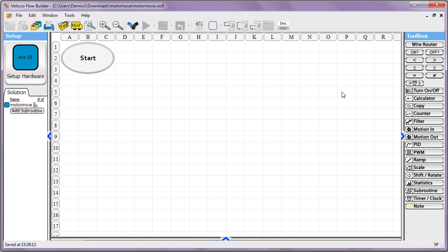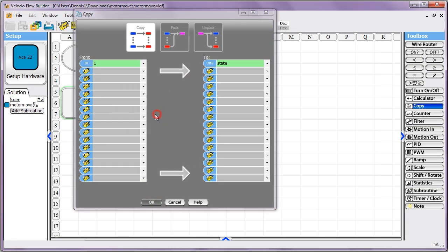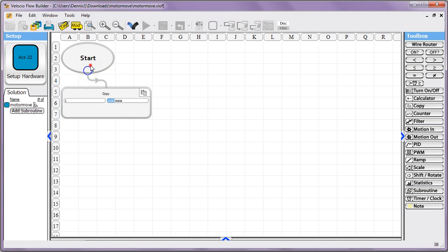And I'm going to set this up like a state machine. You can see in our other tutorials, if you go into the software tab under tutorials, some other examples where we describe state machines, but I'm going to set this up as one. So first thing I need to do is initialize the state machine, and we'll make state a UI16 in this case.